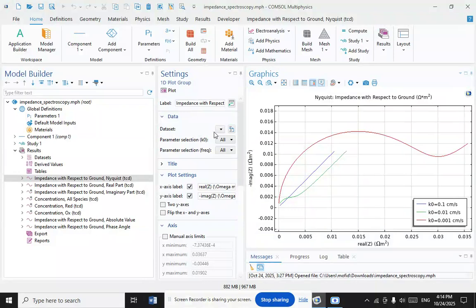Typically, an electrochemical impedance spectroscopy spectrum contains measurements at 60 frequencies over the range from 100 kilohertz to 0.1 hertz. Based on a logarithmic distribution, 10 frequencies per decade takes about 2 to 3 minutes. A comprehensive paradigm on how to estimate the frequency range that is required for the electrochemical impedance spectroscopy study of